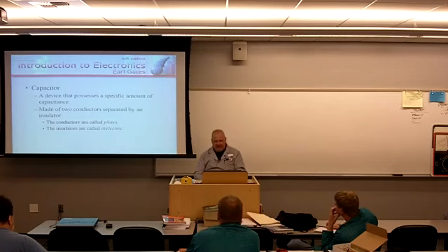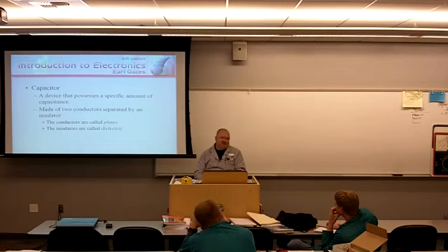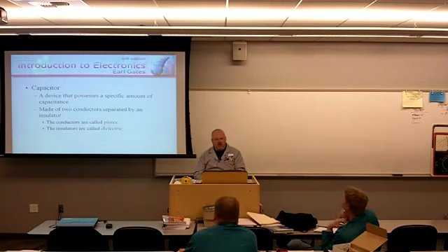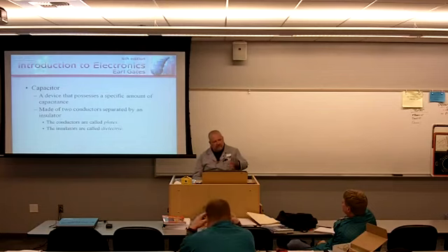Engineers don't want, but we have to deal with it because it's two conductors separated by an insulator. Anytime you do that, you're going to end up with the property of capacitance. Anytime you coil up your welding wire, your welding leads, you're going to create some inductive properties.